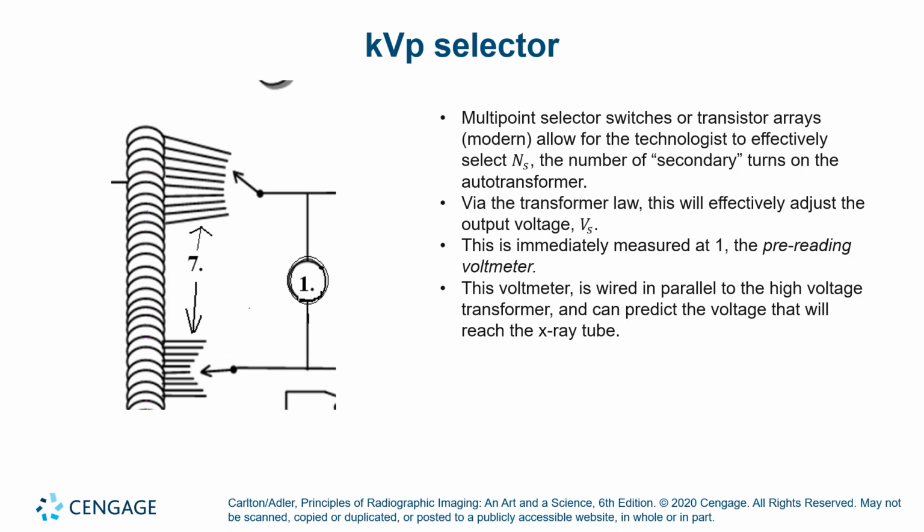And so that'd be plus or minus 2 kVp. And between the two, you basically dial to within plus or minus 1 any kVp number you want between 50 and whatever your generator goes up to. Okay? And again, this is because we can exploit the transformer law via the line compensator such that we're only dealing with the numerators of the transformer law.